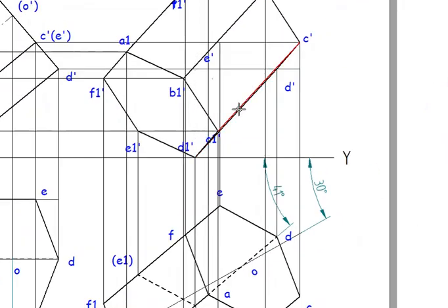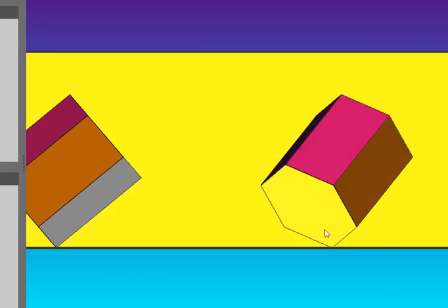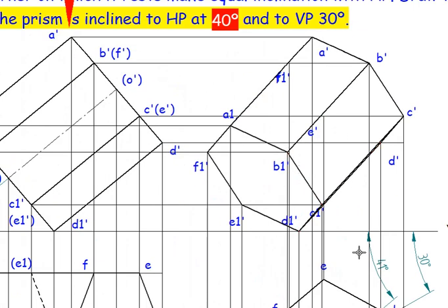So here we are going to be able to see three faces, because the view is slightly changed due to the change of the angle, because I have not kept it for the beta angle. I just kept it 30 degrees by mistake here. So this is the 41 degrees. So there is a view change. So the base is C, three lateral edges is C. So we are going to project the axis line here.